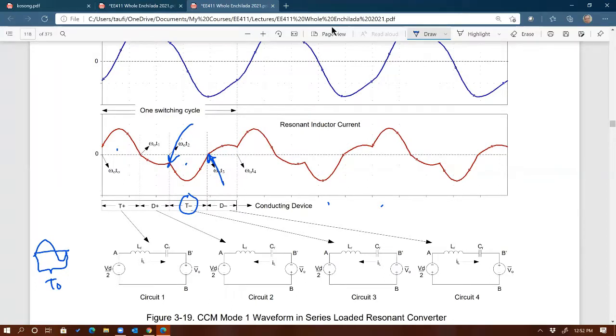Because it's a thyristor. But look, this switch always turns off at 0 right there. So I don't need a signal to turn it off, right? If it's a semi-controllable switch, it will turn off by itself at 0 amps. So that's the reason I'm able to use thyristors: this switch, for this mode, turns off naturally at 0 amps. You don't need to force the switch to turn off. It will turn off by itself because it's seeing 0 amps already before the current is taken over by the diode across it. Okay, hopefully that's clear.